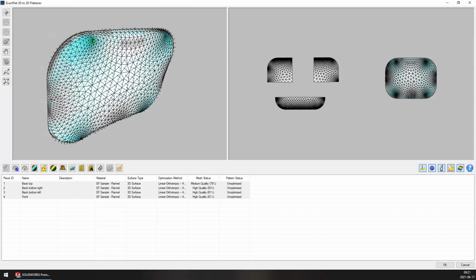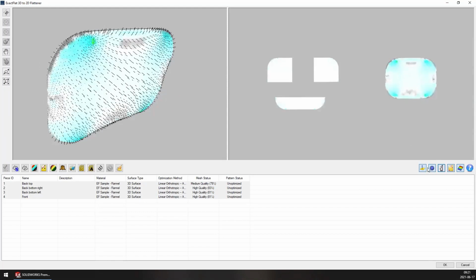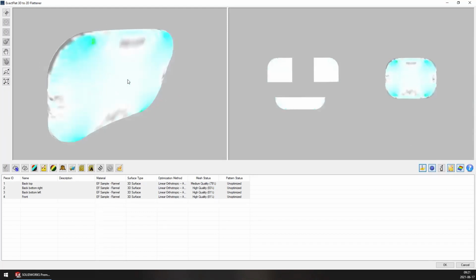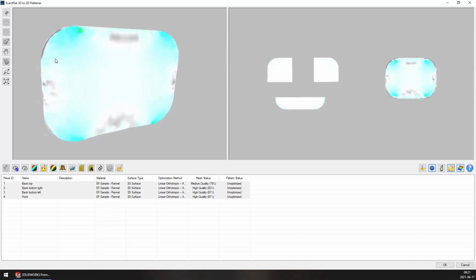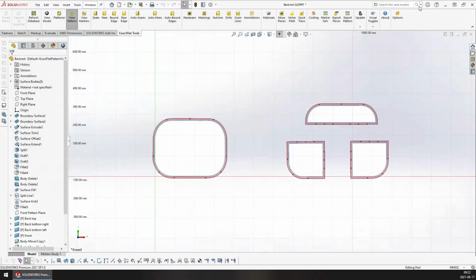So we can see the effects of the strain map. I'll just turn off our edge highlights and our piece normals over here. If I were to change these, there's lots of different ways we can use the strain map to our advantage. One way is to use it to indicate a very hard limit. So if we are good for anything up to a certain amount of strain, we can use the strain map to tell us the second we've violated that strain constraint.